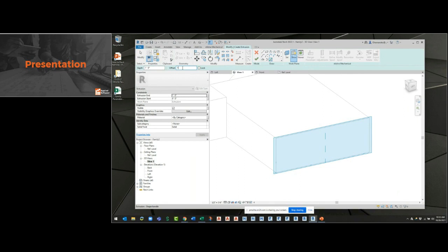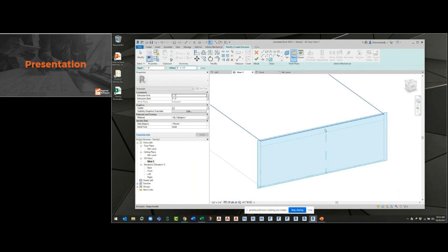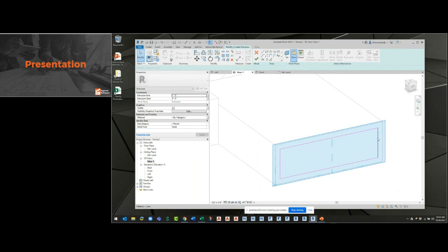So I'm going to say I want to offset, say, 1.5 inches from the top. And I'll hover over the edge here of the top, and it's going to offset 1.5 inches off the top and the bottom. And then off of this side over here, I'll go ahead and give it the 1.5 inches offset to the inside, and then I'll clean up my sketch, hitting escape when I'm done with the sketch, using my trim command right here to trim this out, making sure I clean it up, make sure it's a closed loop, right? And now I can use my dimensions here and say, well, let's see, it should be 1'4",